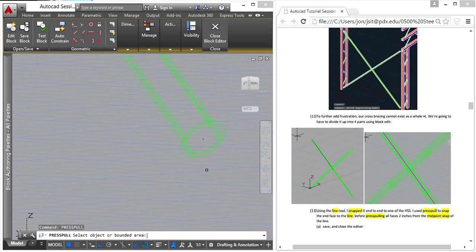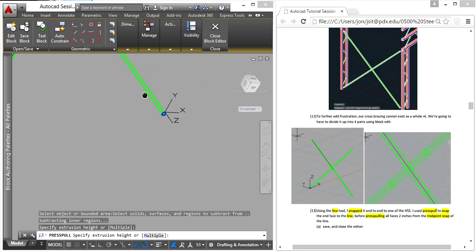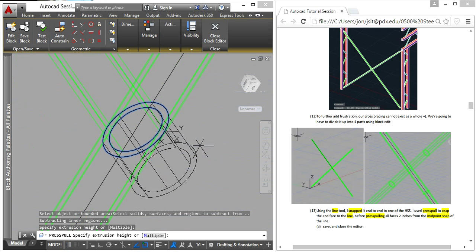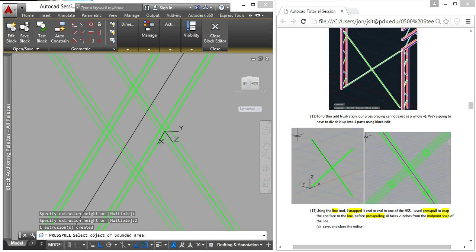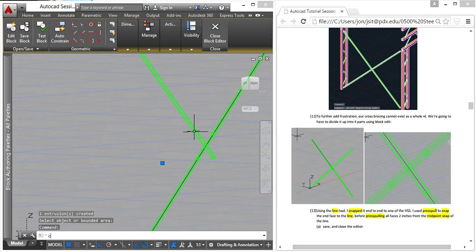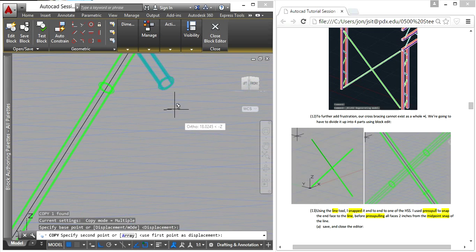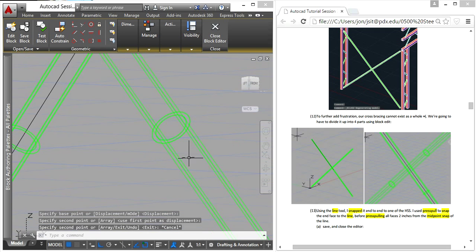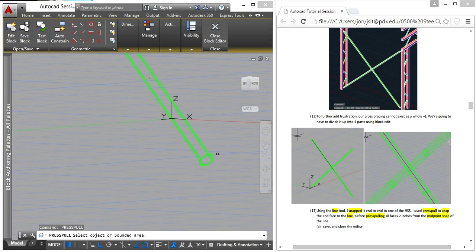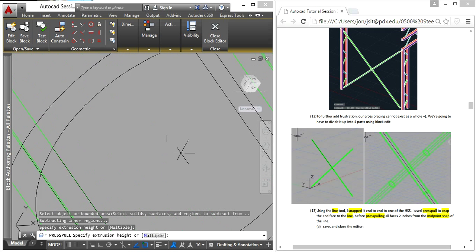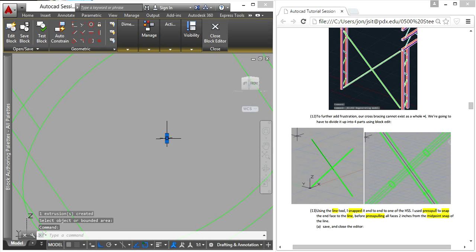Remember that the top is our center. So we're going to press pull all the way to that center line, and we're going to pull it out, let's say 2. Keep it kind of uniform. And we're going to make a copy of that from there to there. If we did this right, it should be longer by 2. When in doubt, we always have that line over there. That's why we draw the line. Remember, it connects to the top. When you're done, delete that line because we no longer need it to measure.